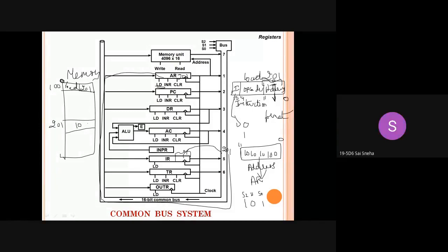Data, ma'am. So will you place this data in the instruction register or in the data register? Data register. Yes, you must know the difference. So this data must be placed on the common bus. For that, again the selection lines S2, S1, S0 must be what, ma? For placing whatever we have at that address. 011. See this, we are in memory. Memory has to place the data at that address on the common bus. With this common bus it goes to the data register.